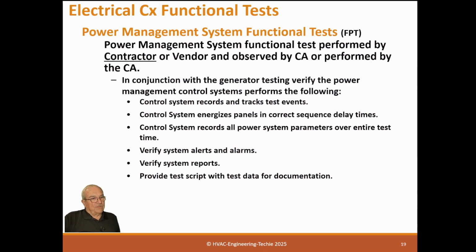So what happens is when you have a system on emergency power and the power feed fails, the generator comes up and runs, accepts the load, and the ATSs start switching the load. Well, if it's a big job and you have a whole bunch of breakers and loads out there on an ATS, once the ATS switches and they power up, it will start bringing those breakers over in a sequence so they don't load up all at one time, thus causing the generator an issue.